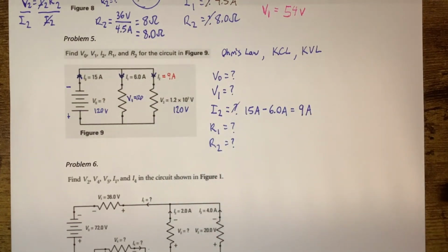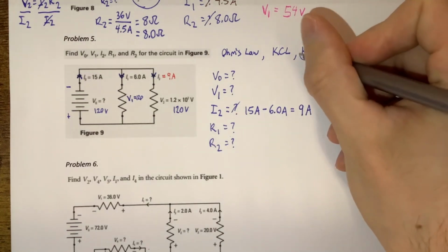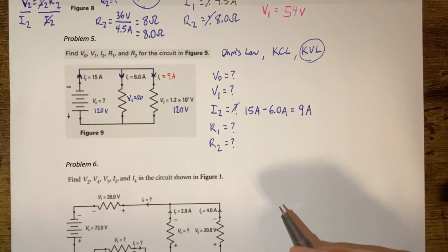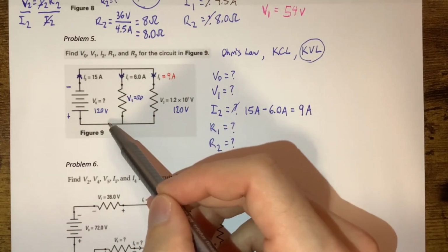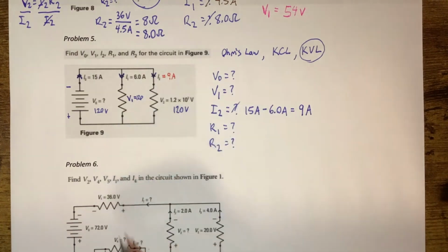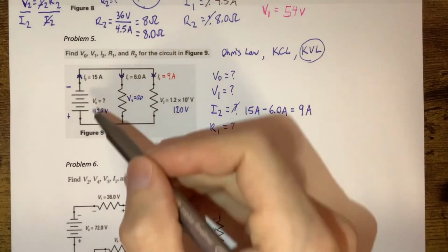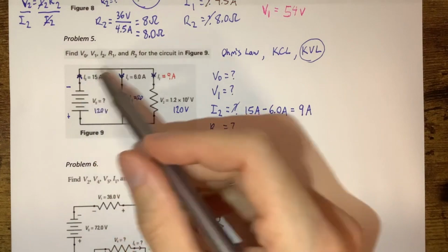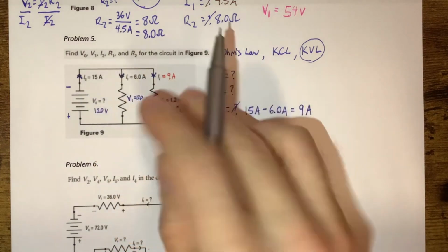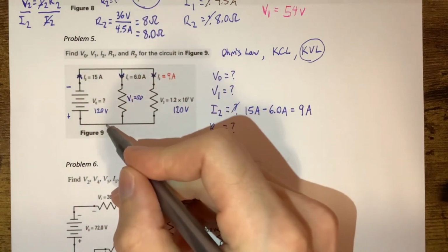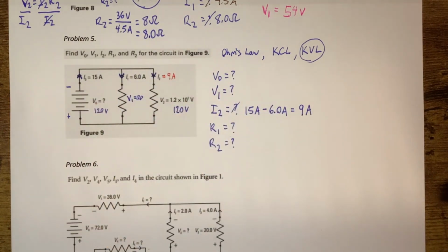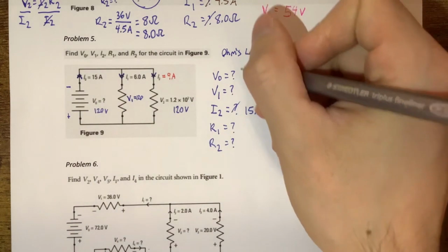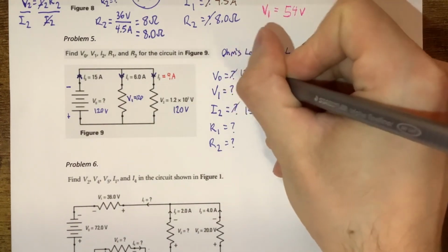So hopefully that analogy helps a little bit. And that is kind of validation of Kirchhoff's voltage law here, okay? Because ultimately we need to be at 0 volts over here. Otherwise, we're saying that energy can be created or destroyed. But we know energy cannot be created or destroyed. So if we had these electrons up to this energy level, 120, we're going to go 120 down these, and then we'll be at 0 here. Okay, and then the thing will just completely go through until the battery burns out, okay? So we know what V naught is. That's going to be 120 now.